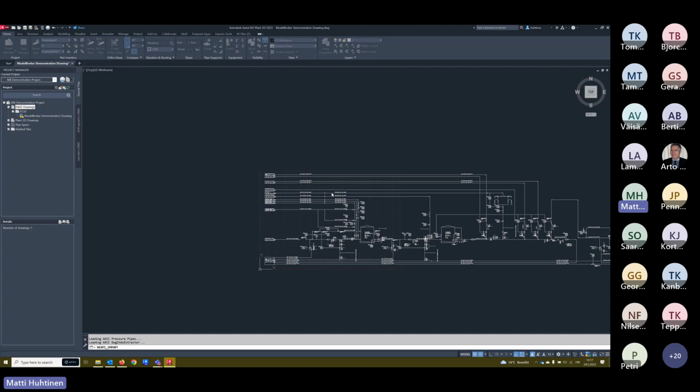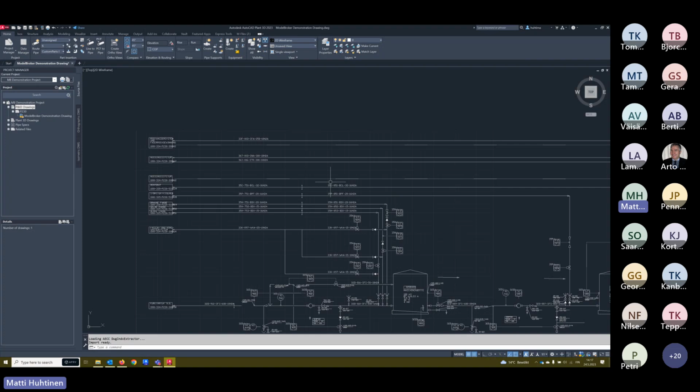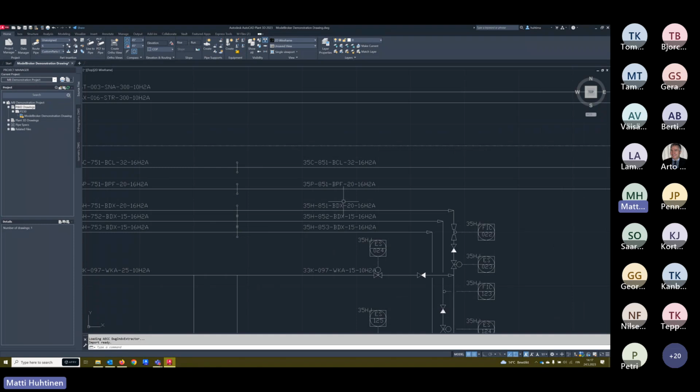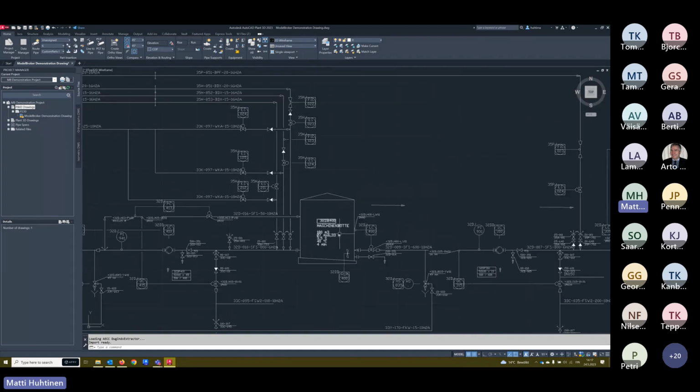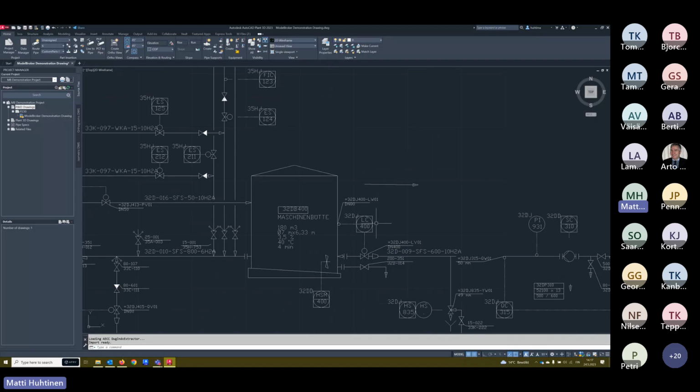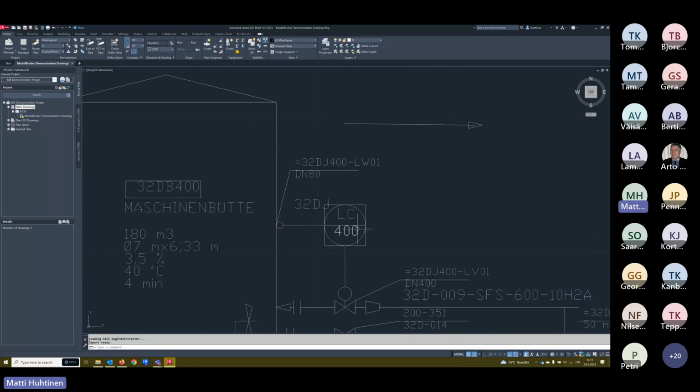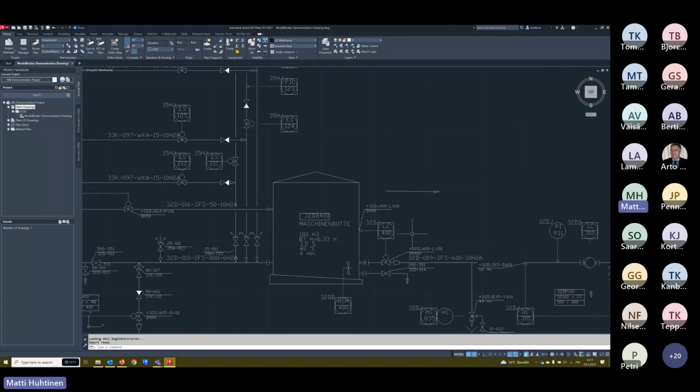And then we can choose if we have it. Of course, that depends also on whether we have a non-intelligent diagram where we have no information, for example pipeline numbers or tank equipment IDs. Then it's practically impossible to use the model broker tool if we don't have informative PNIDs. But now we have all the line numbers here, we have tank IDs here, we have loop function and loop number here. So everything we can put into the Plant 3D database.